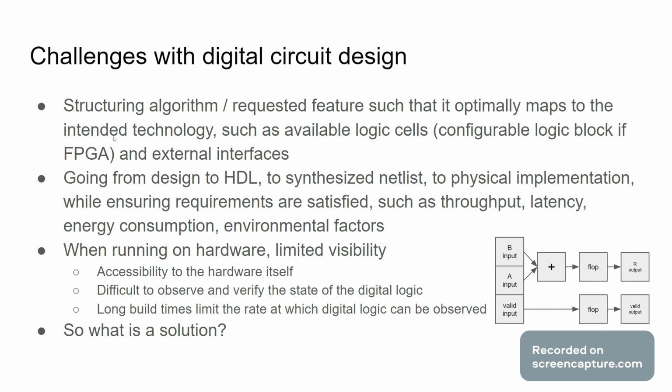So with that out of the way, one of the major challenges is just taking some starting algorithm or a feature, and then targeting that algorithm so that it maps better to the underlying technology. An FPGA, a field programmable gate array, is an array of configurable logic blocks where each logic block could be configured to run as combo logic or sequential logic flip flops, and they're all routed together. So you're building a circuit, in other words. So something simple as an adder, or you have a bunch of math, you have to break apart, and then you section each piece off so that you can maximize your throughput. So that's one challenge in itself.